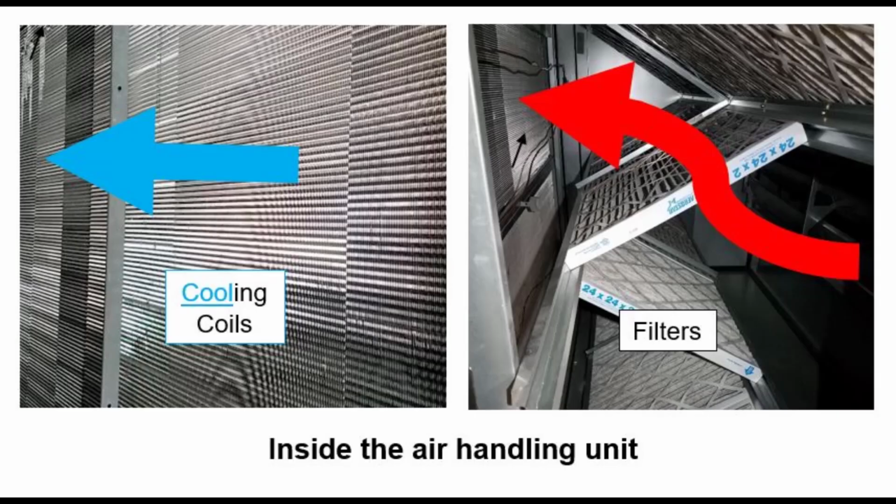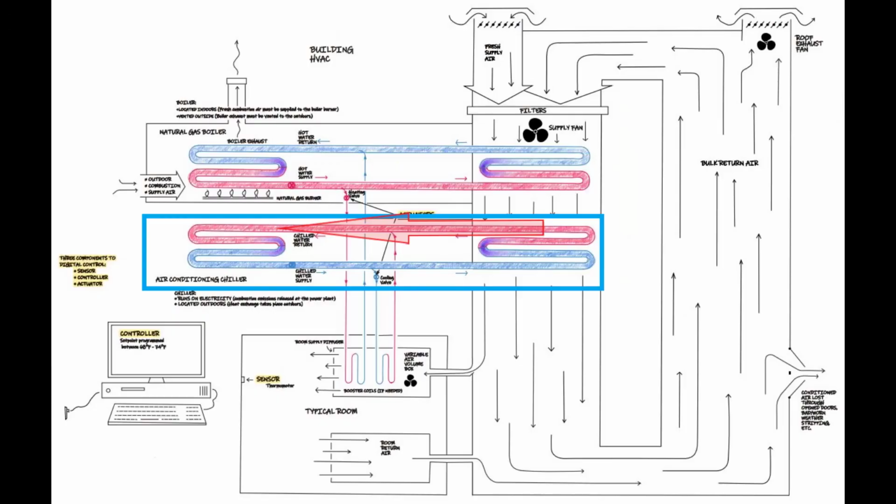The air conditioning heat exchanger, usually called a cooling coil, probably resembles the one for the boiler in the air handling system. But here, as warm air is forced through this coil, it is cooled and dehumidified. Then it's circulated throughout the building. Of course, the cold water in the coil is warmed in the process and is sent back outdoors to the chiller again.